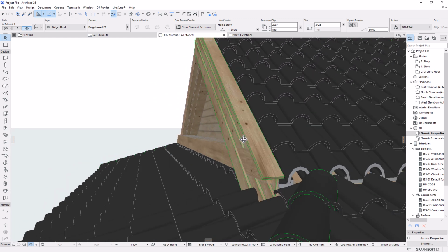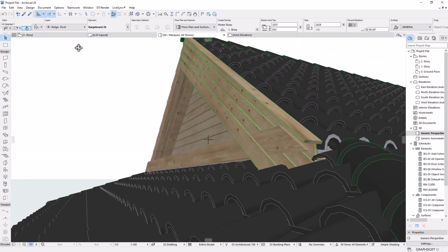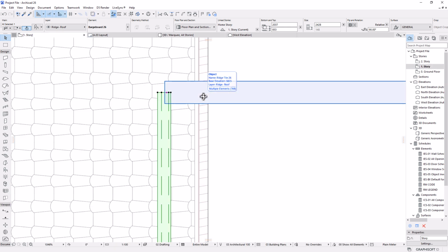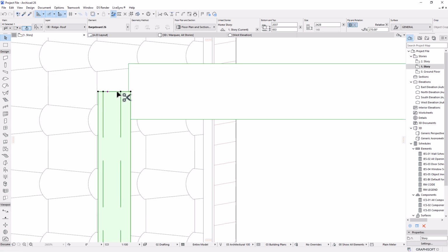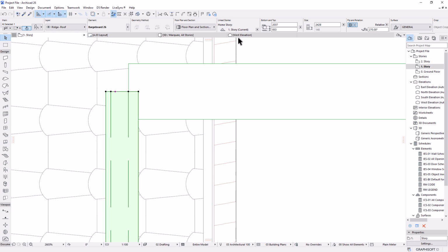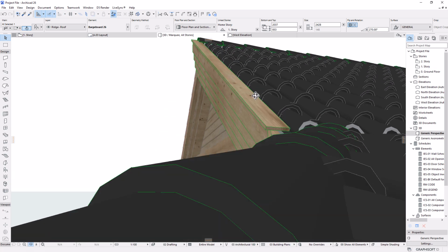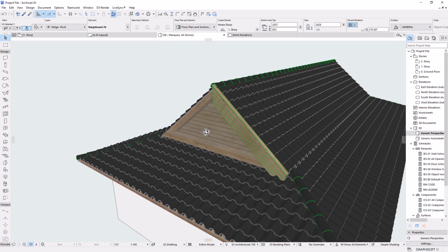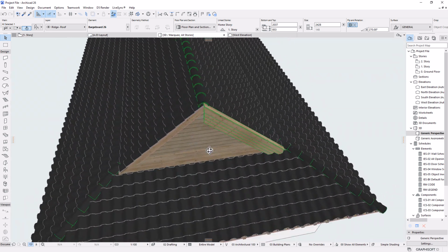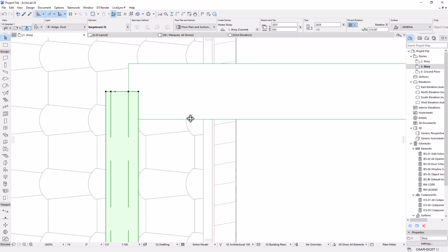I think we need to mirror it because this side is supposed to be the inside of our board. So I would Control M, let's pick just one of the points and then activate the mirror like that. Move it back to the edge of that. If you check on 3D, you would have this because it has to close on top here to create more of a flashing for your design. That looks fantastic. Now let's mirror a copy to the other side by Control Shift M on your keyboard and use this horizontal mode. Perfect.